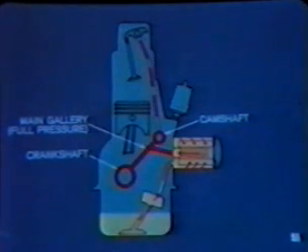Operating at a pressure of about 50 psi, the system pumps oil first to the main oil gallery, which feeds the crankshaft and camshaft. Thus, full pressure lubrication is used for the camshaft journals, the hydraulic lifters, main bearings, and rod bearings.